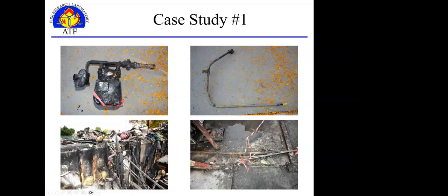And if you're going to do any sort of computer or calculation based analysis, you need to actually record and document the lengths and the diameters as well as all the fittings, because every 90-degree bend and fitting affects the flow rate of that gas. So we would have to document all of this. This is a 2-foot section going into a 90 with a 2-inch nipple, and then another 90, and then another 90, and all of that has to be documented.